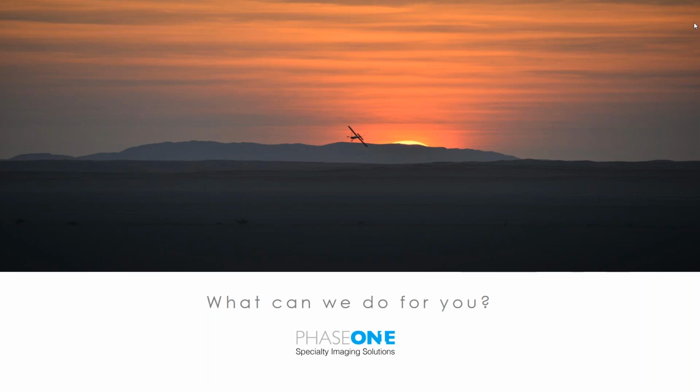Hey James, this is Paula. There's one question that's just come in asking, does IX Flight have the ability to display the image footprints? Yes, it does. So IX Flight, you can configure it to show not only the image footprints, but you can also ask it to show you the stereo models. So everything that is created in IX Plan is basically shapefile based. So anything that is created inside IX Plan or IX Flight can be exported as shapefile.